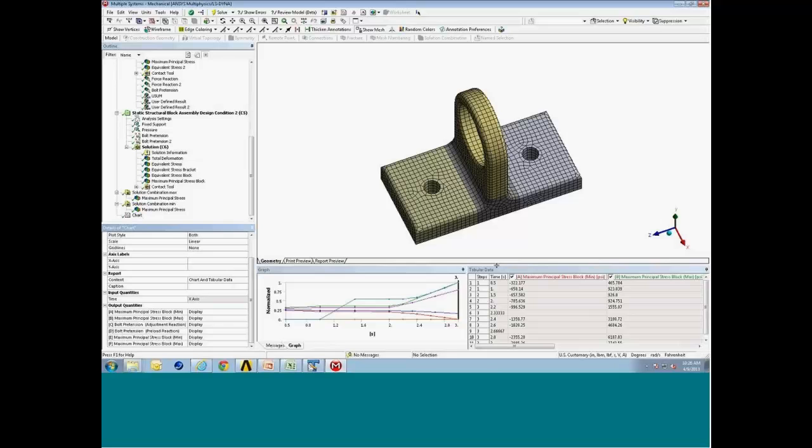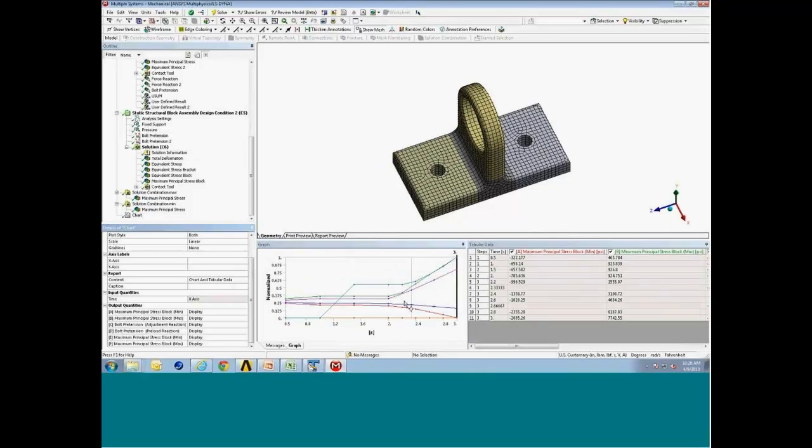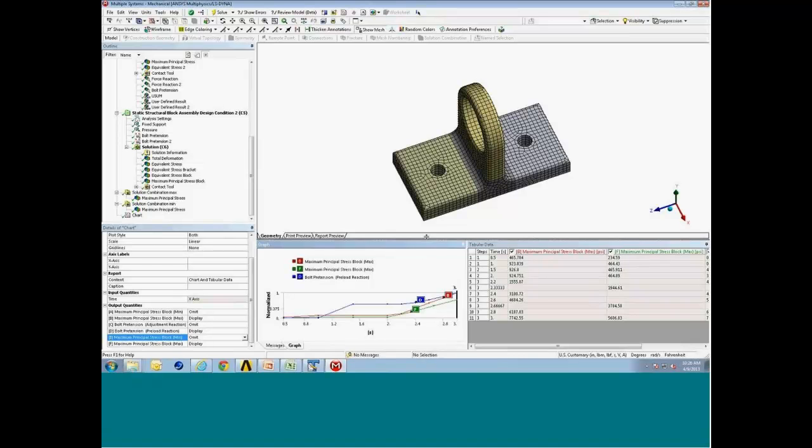You'll see down below, let me expand this a little bit. You can see our chart here, identifying all the quantities, the results with time. You have control on the axes and the output quantities. What's nice here is you can also choose to only display certain quantities from the items you select in terms of min and max. And so if I just wanted to display the maximum, I can go down to the details pane and omit certain quantities in our results. Let's get rid of all the mins, and now I have a little bit more concise data to show here. And you can turn on the legends just to identify these a little bit nicer.